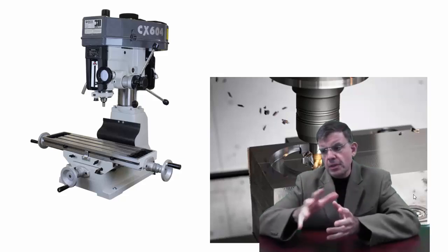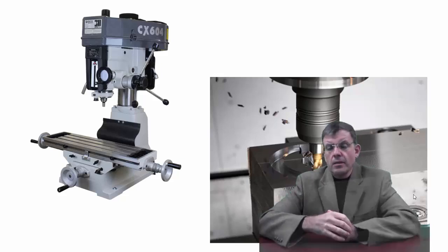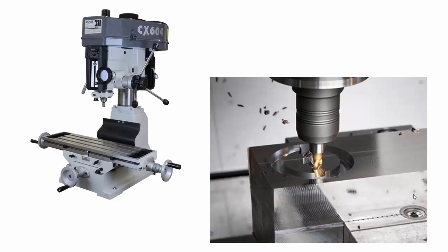Just to illustrate the concept, this particular one has 3 axes of motion, so you can move the bed left and right and also in and out. And then you can, of course, plunge the cutting tool through its Z axis. Again, extremely versatile machines. You can augment the number of axes with the addition of a rotary table. You can generally go up to 5 axes with these machines. Of course, the 6th axis would be the rotation of the tool itself. So unlike a robot, in a CNC you don't normally see 6 axes, or at least 6 independent axes.